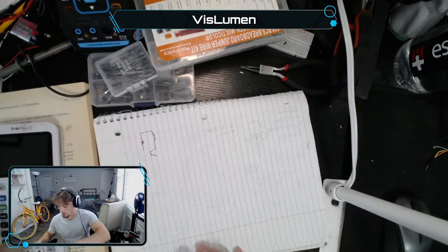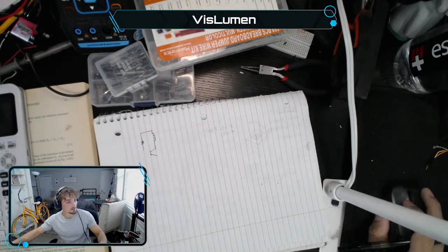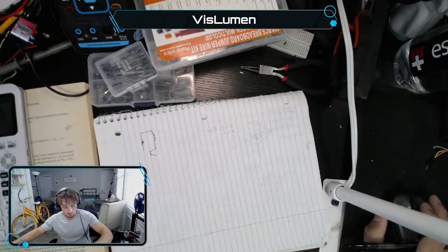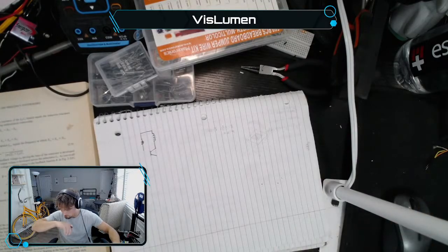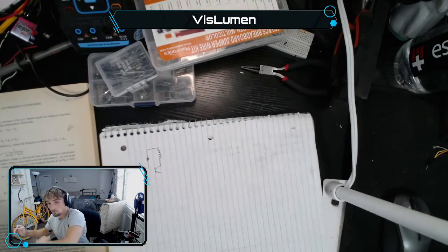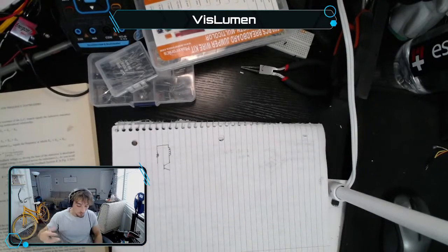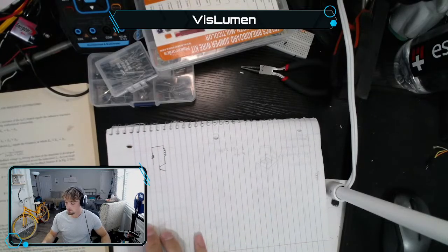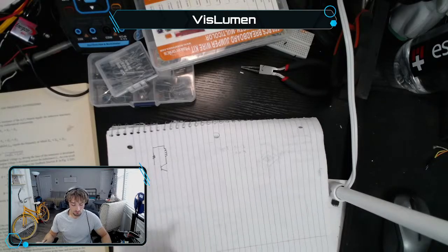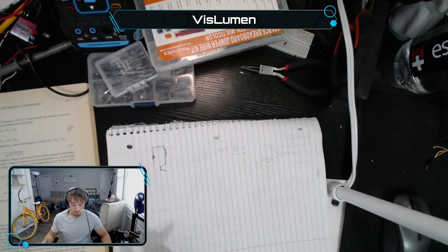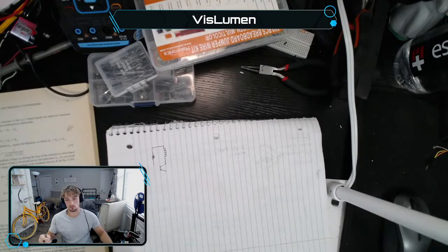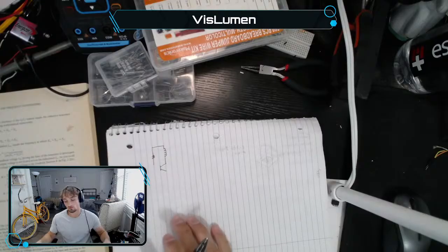And this is where we were at. I guess I kind of understand that, so this is where we're at: the Hartley oscillator. Okay. So we're going to use the common emitter amplifier to amplify a feedback signal, and continue to do this in order to generate oscillations or generate a frequency.